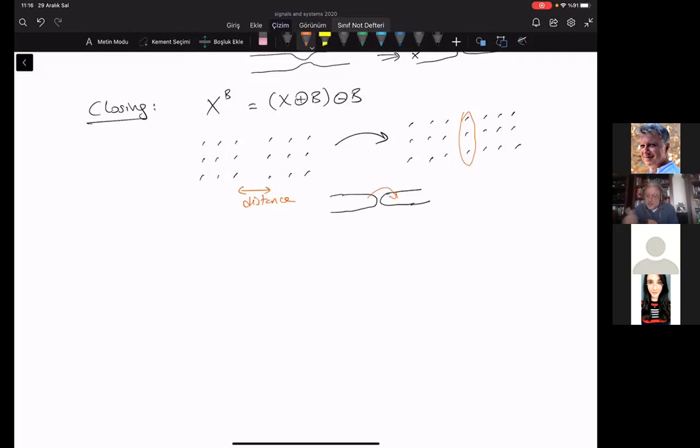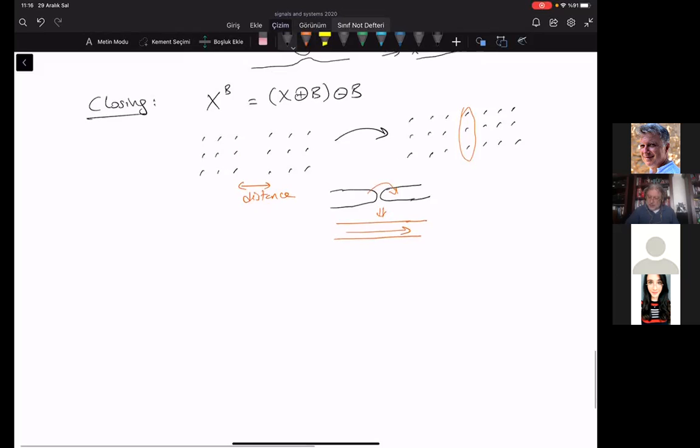And if you apply closing, it will close up everything and show that they seem to be connected, which is an error, of course, that is easy to detect. So closing is an inspection tool to see whether two objects are too near to one another or not, because they will be merged using closing. Now, these are the easy ones to understand, and they are very fundamentally utilized in automation systems with imaging.